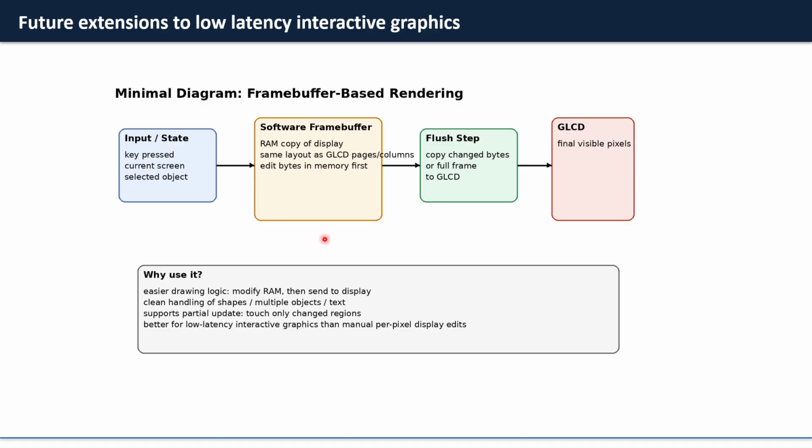We can write only on the important parts of the screen which are changing, instead of overwriting every part again and again. We can do that on the GLCD too, but interacting with the GLCD for every small task induces a lot of latency. It is better that we first fix what we want to change and then we interact with the GLCD.